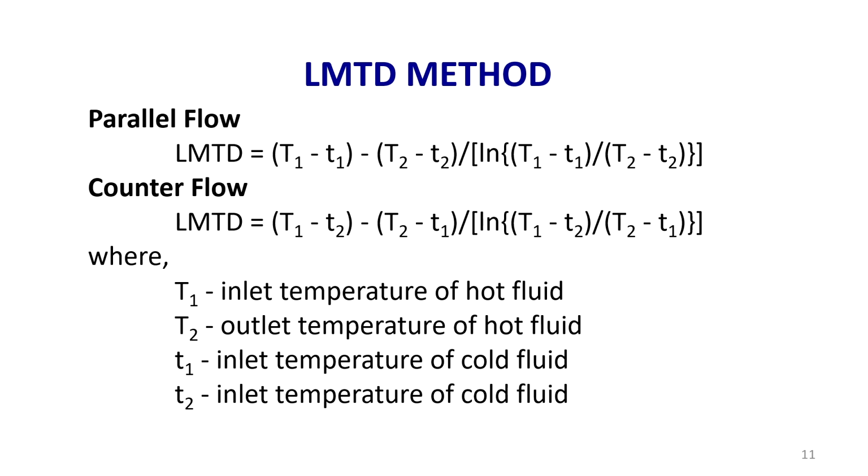So, that is also taken into consideration in U, but if we neglect fouling resistance, on the tube side as well as on the shell side, then 1 by U will be equal to the thermal resistance due to conduction and the resistance due to convection. These are all derived equations.